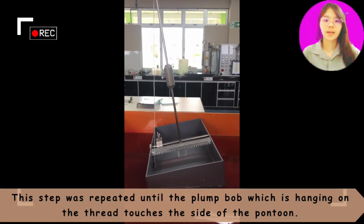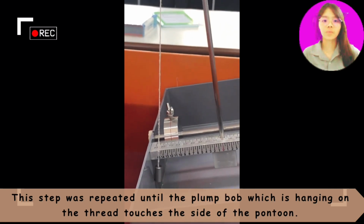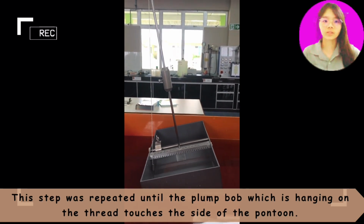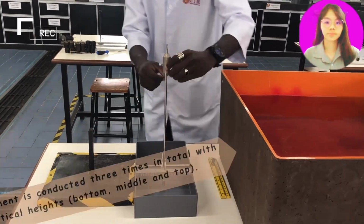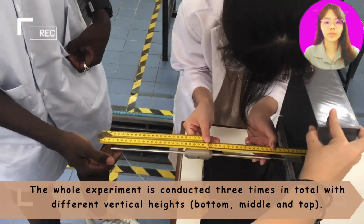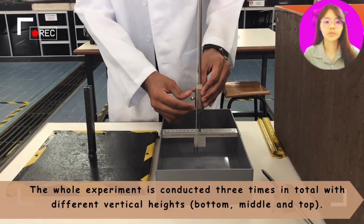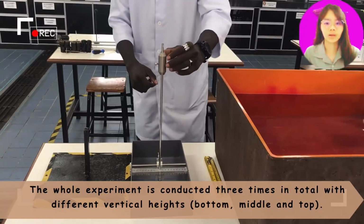The previous step was repeated with an increment of 10 mm until the plumb bob, which is hanging on the thread, touched the side of the pontoon, and the same step was repeated on the left side. The height of the vertical weight was adjusted, and then the previous procedure was repeated. The whole experiment was conducted 3 times in total with different vertical heights: bottom, middle, and top.